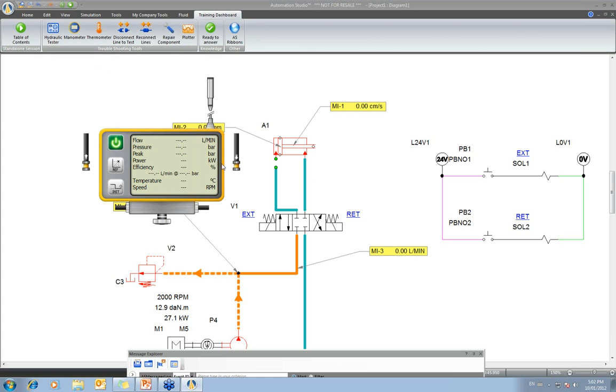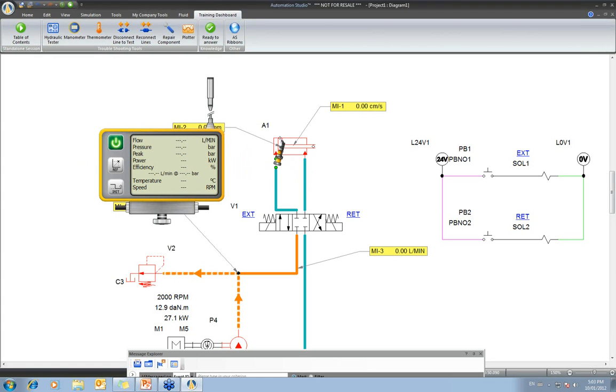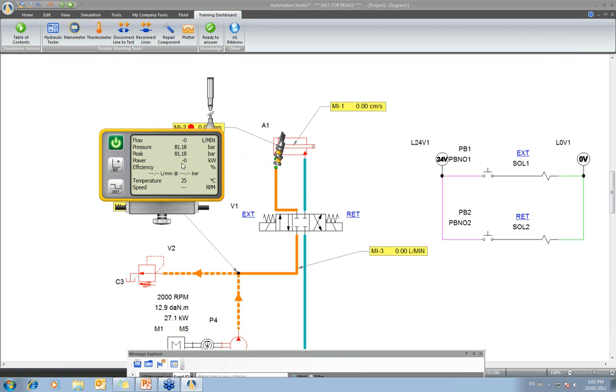So you can turn it on, and then you can connect the hydraulic tester from the inlet to the outlet. There we go. And then you can read the pressure over there, and of course the temperature if there's any temperature change. You can even have a cracking pressure that you can increase from here as well if you want to load test the circuit. So it's a really nice tool to have.